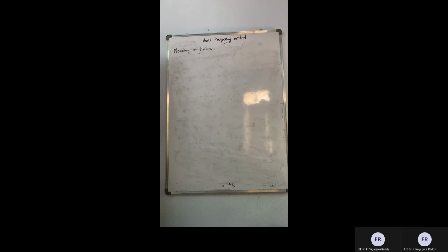In the last lecture, we have seen the modeling of speed governor system. In today's class, we will look into the modeling of the other components of load frequency control of a single area. So now we will be discussing the modeling of a steam turbine.